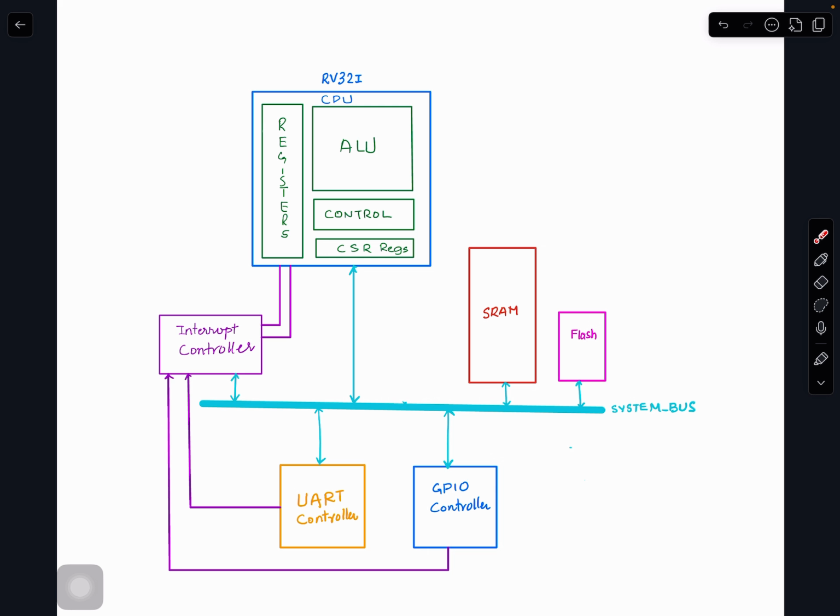Their thing is they have an address bus, data bus, and control bus, and all these devices are connected to them. The CPU acts as master, and these are all slaves in our system. But they all communicate through this. If this wants to access something here, it sends an address through here. And each device knows when the address is coming for it or not. We'll look into some examples.